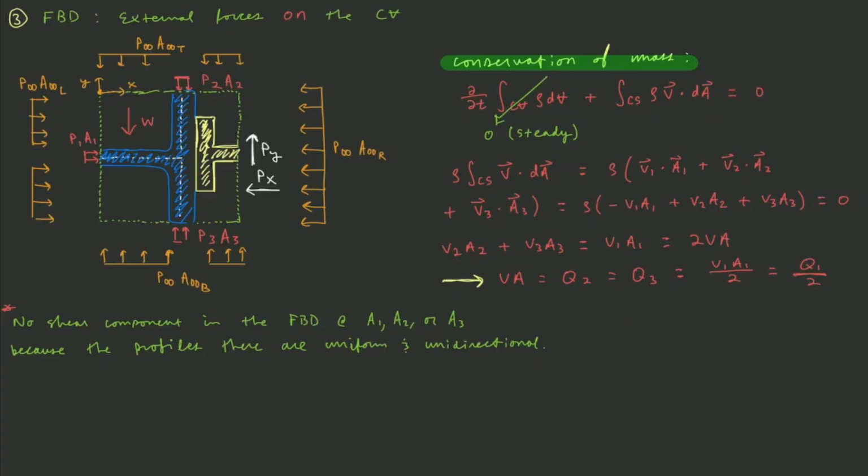Now we need to explain where these v dot A's come from. How do we get v dot A from this integral, which has v dot dA? Well, let's work this out. If we have an integral over our control surface of v dot dA, and we know that we have 3 terms that we really care about, we've just gone over that: cross-section 1, v dot dA, plus cross-section 2, v dot dA, plus cross-section 3, v dot dA. We know that these can be simplified as follows.